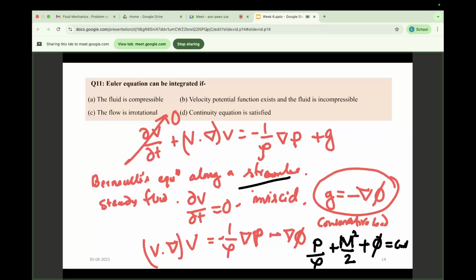Okay, so in this question it is not clear, a potential function is given, right? So it is given a potential function. I can't say anything about rotationality or irrotationality. I have to check whether the double derivative of this one is 0 or not. So accordingly I can solve this one, right?